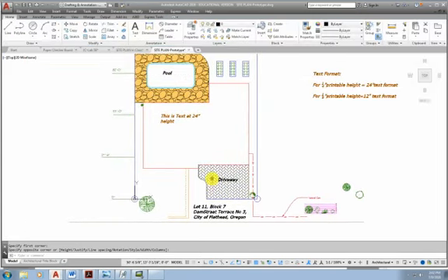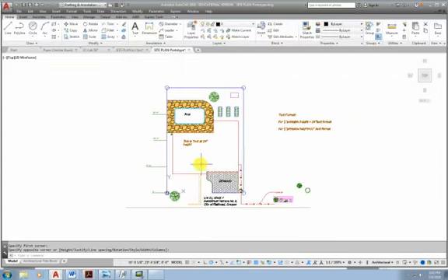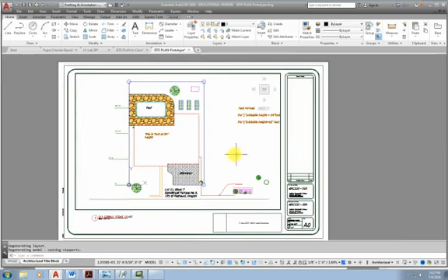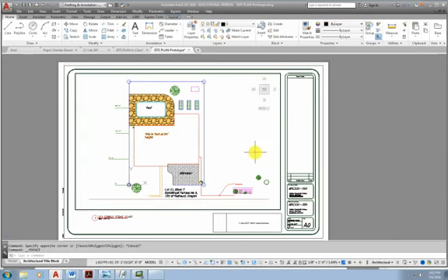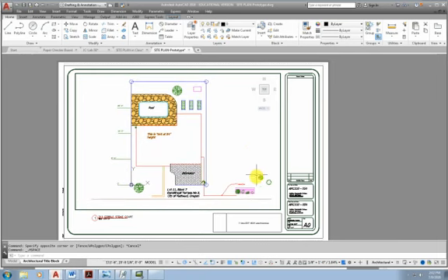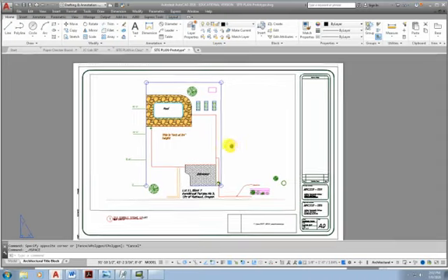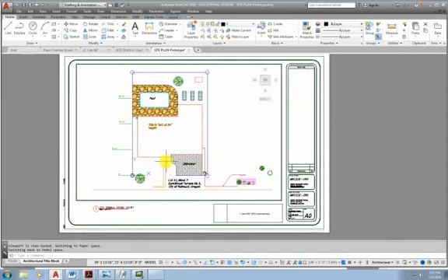And then lastly, we're going to put this onto a title block. And so what I'll do is I'll click on the architectural title block. And then if I double click in the viewport, I can see I've got it set at 1/8 of an inch equals a foot. It's perfect. I'll cut out this text instruction. I don't need it. You'll notice I can double click, I'm on the title block. Double click, I'm in the viewport. And so what I want to do is lock in that scale. And now that the scale's locked in, it won't change.